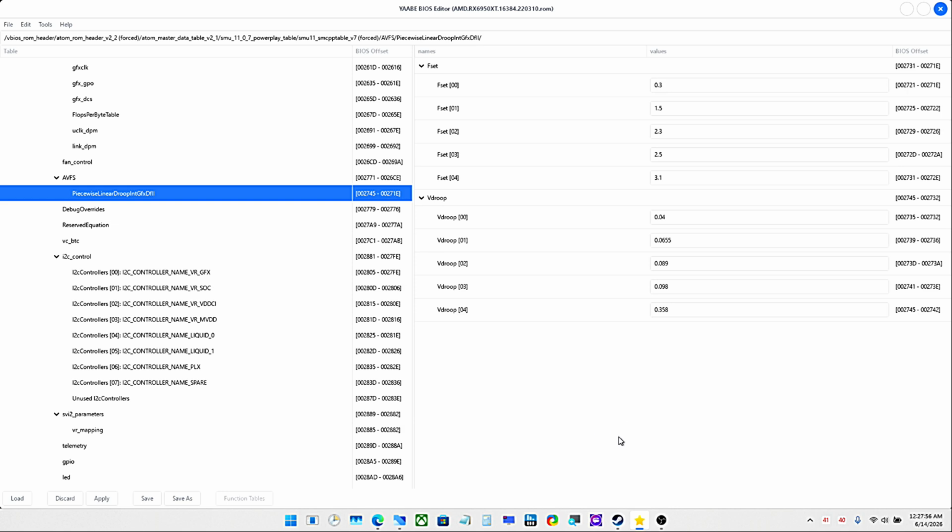It's got to droop. The V droop occurs anyway with the heating of the electronic components, the power components which power the GPU in the first place. The V droop occurs because the phases aren't cooled, and they just keep getting hotter and hotter, and the droop gives more and more.